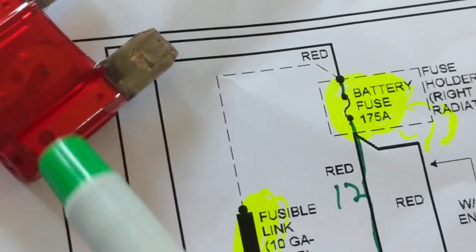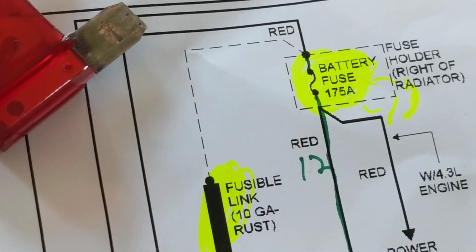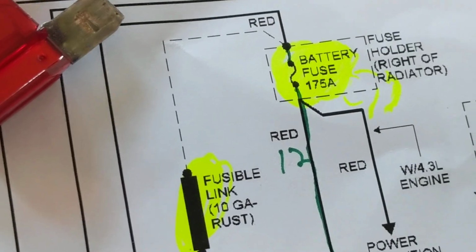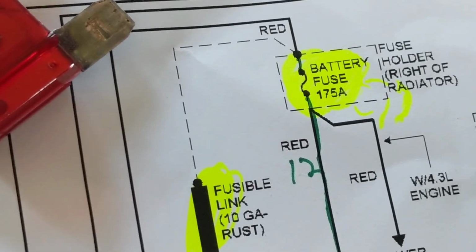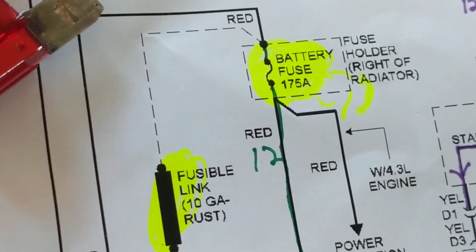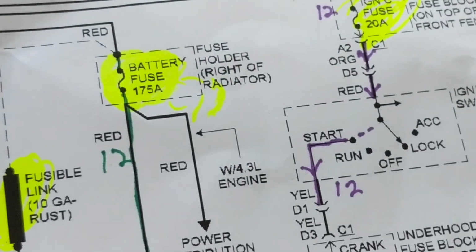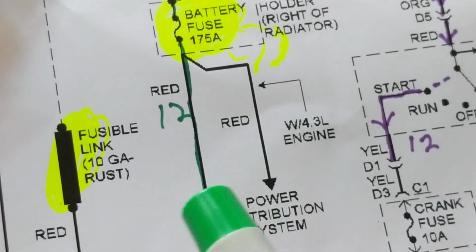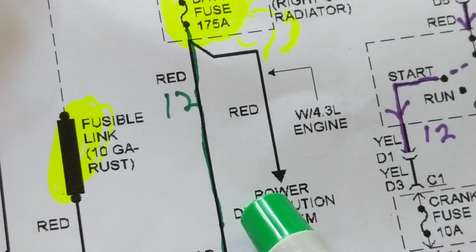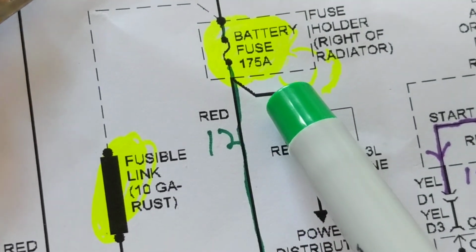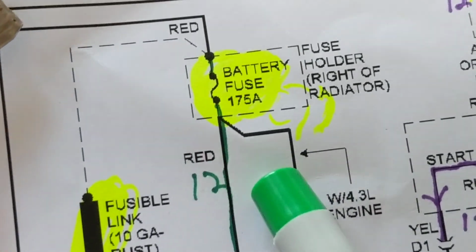Is it important to know the color? Well, yeah, it's easier to find the fuse. Let's say sometimes on Fords or something, they're not too good on the fuse panel, on the fuse cover, to give you the exact location. So when I look for a 50 amp fuse, I'll look for a red fuse. Again, since it's a 50 amp fuse, I'll go for the big ones, the maxi ones.